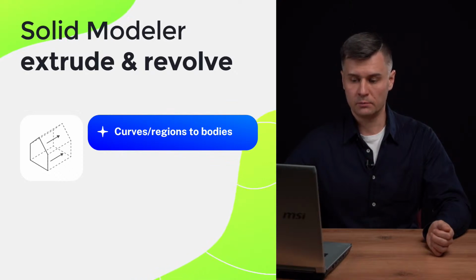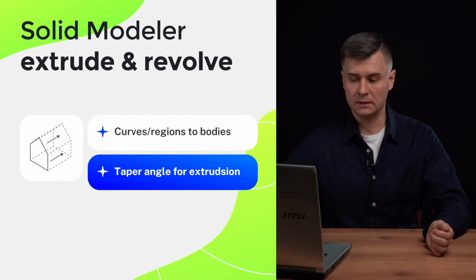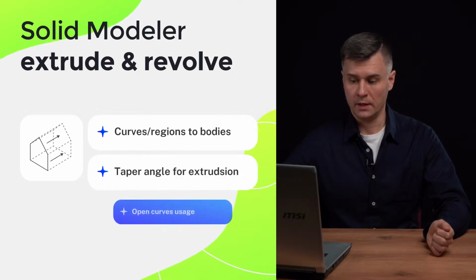One significant improvement we have made is the addition of support for taper angle in the extrusion functionality. Currently, there are a few limitations. It doesn't support a profile with a spline curve, and it doesn't support creation of an extruded surface from a polyline that intersects the line between the polyline's endpoints. The unsupported cases will be implemented soon.